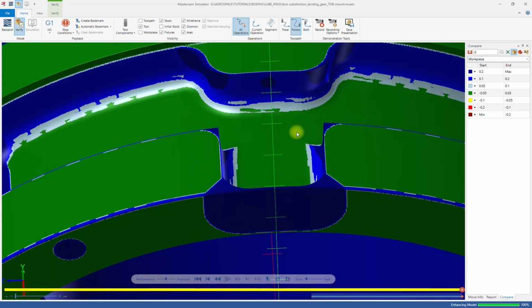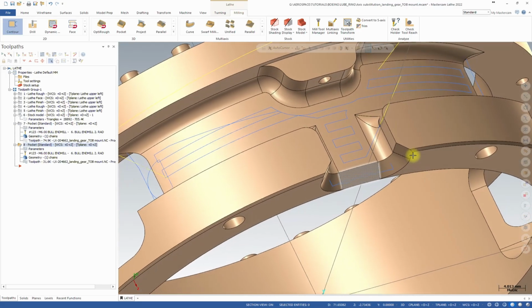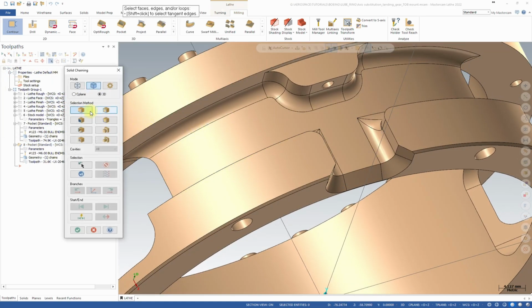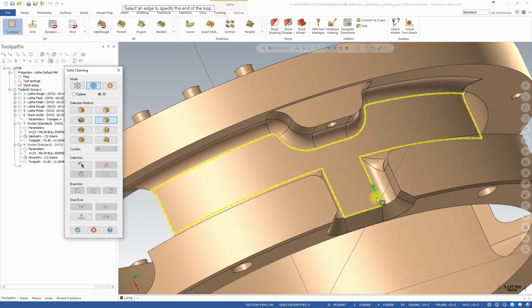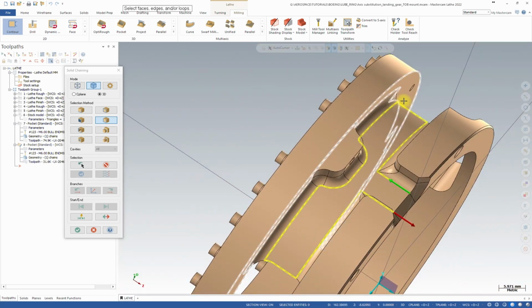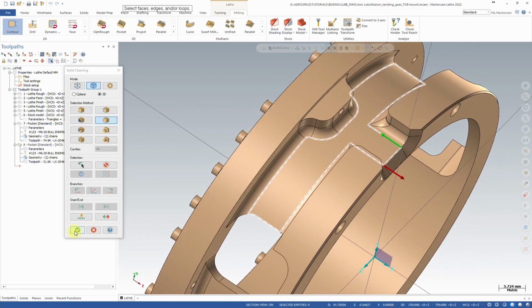First, we're going to take care of this front material, and now we have even thin wall because we left stock everywhere on walls, and then we are going to finish the walls. So how can we fix it? Let's go to geometry. I'm going to rechain that again, and this time I'm going to use a partial loop, and I'm going to select this chain starting here, but instead of going around up to this point again, I'm going to finish here. And in this way we have all that closed, only this side is open.